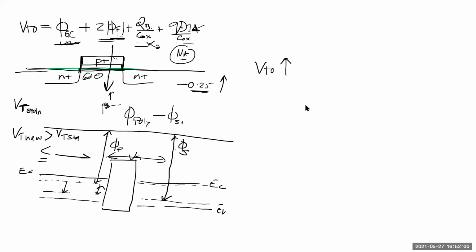So the only thing in that equation, ideally, which is changing is the contact potential, the difference between the Fermi potentials. Yes, Ashwini and Swadesh were saying that the Fermi potential will decrease. Correct, which means that the work function will increase, which means the difference between the work functions will decrease, but it's a negative number, so your VT will actually increase. Will become more positive.